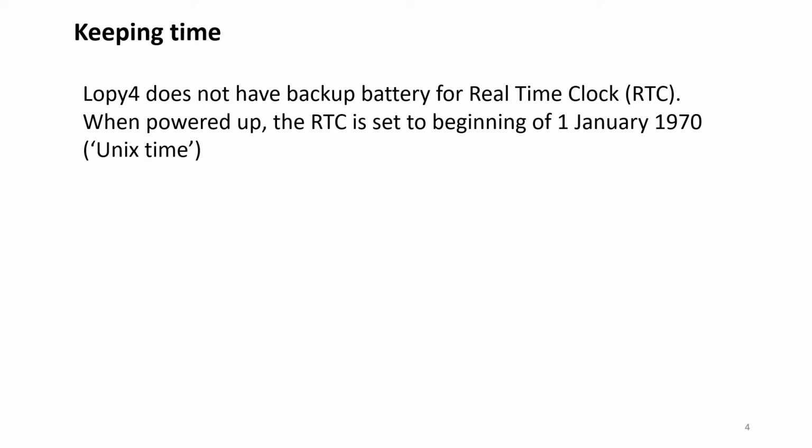In any IoT system, time is very important. That's why for IoT systems for hydrologic measurements, we have to pay attention to time and set it at the beginning. Advanced electronics such as a laptop or mobile phones, that is the smartphones, usually keep time continuously. Therefore, whenever you switch it on or off, it's always keeping time. This is because they have a backup battery installed within it that powers the real-time clock.